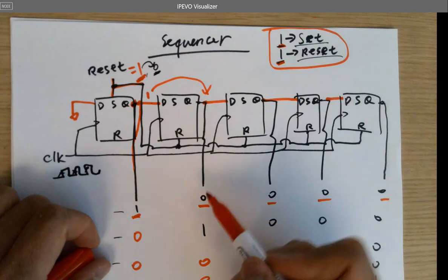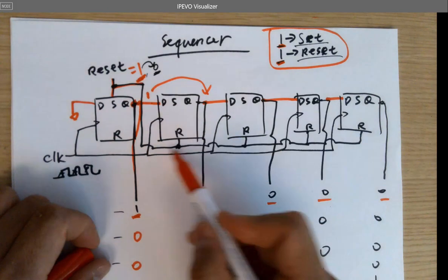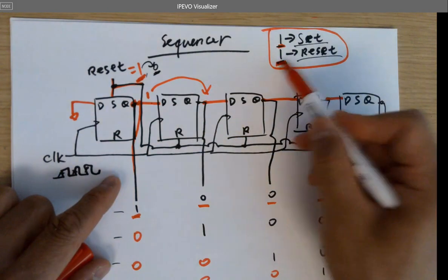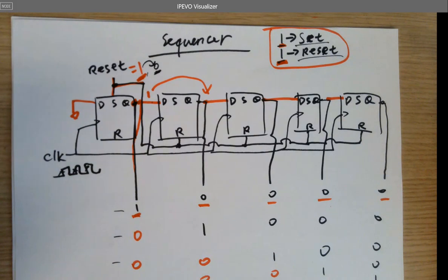You're making sure you're getting 0 for the rest because whenever I put a 1 here, it resets all of them. So that first one, when you write one at the start, it's like initializing everything. Basically, yep. It's setting the first one and then using the reset pin to set the other 4 to 0.